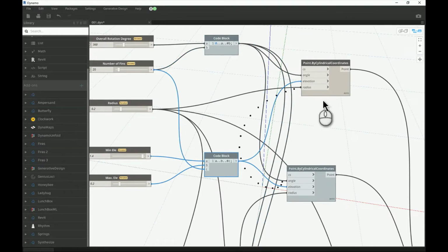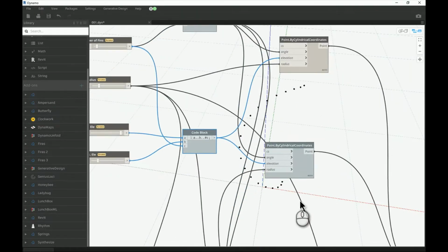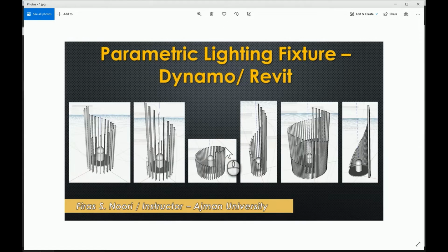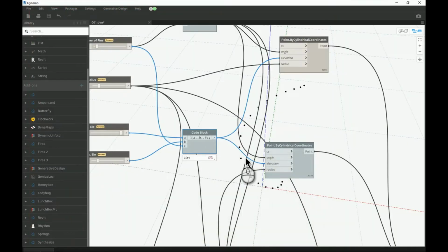And that's the first thing. That's the first helix. Now we need a second helix. The second helix, if I want to go back, will determine the thickness of those. If you zoom in here, you find that there's a thickness for each fin. So how to do that again is to set another set of points.